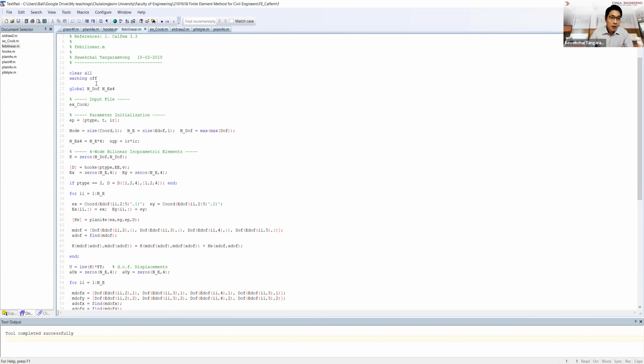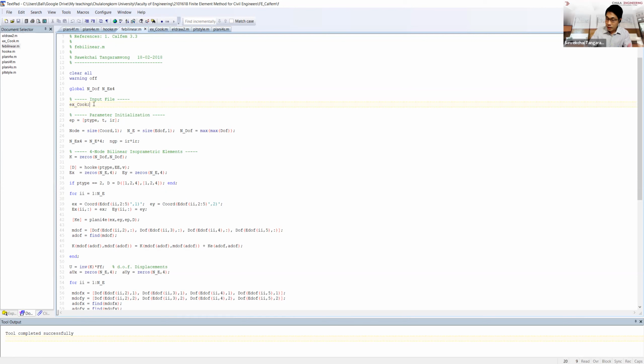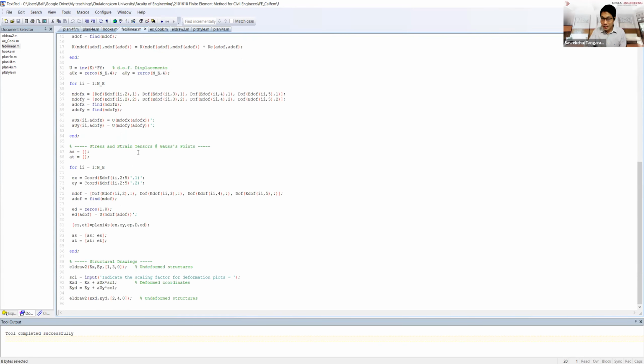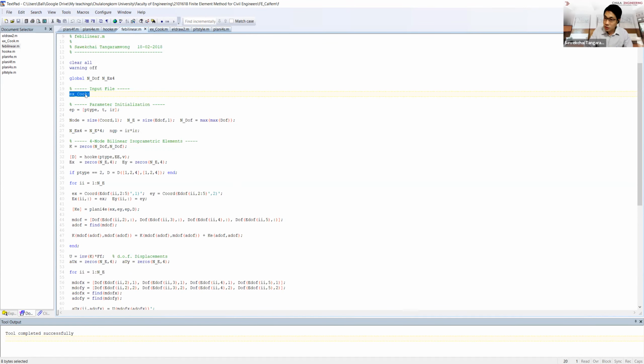And if you have a look here, I have put them in the different framework, starting from the input files, which is according to what input you want to have. For the structures, you might name them, for example, structure A, structure B, structure C. Every time you change the structure, you just change these input files. The rest of them, you keep as is, and that will construct the matrix Ki, Bi, assemble the global K matrix, and assemble the force matrix for you, right? You just need to have this to be correct.